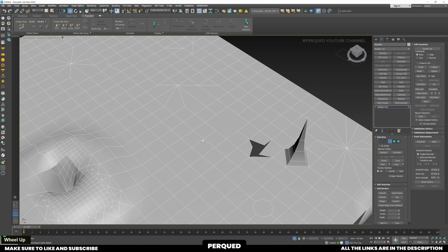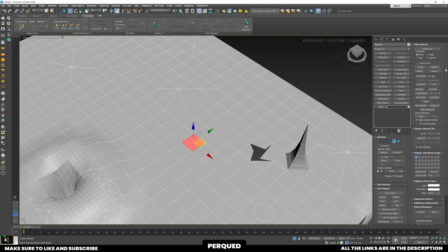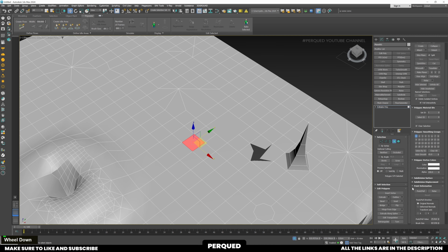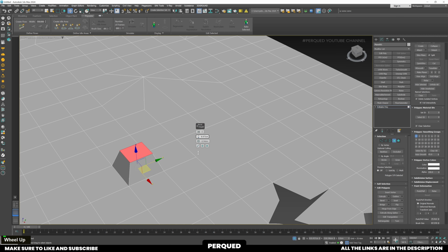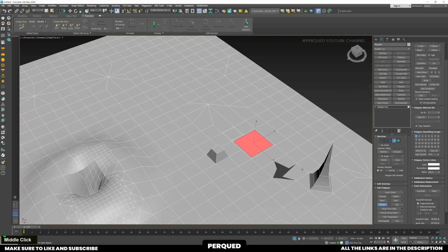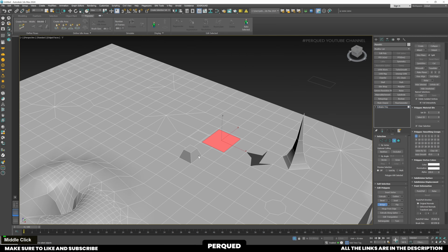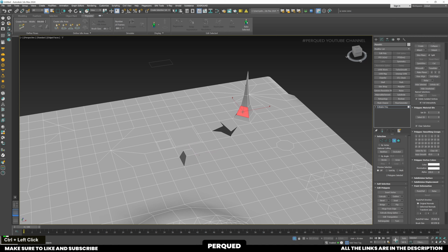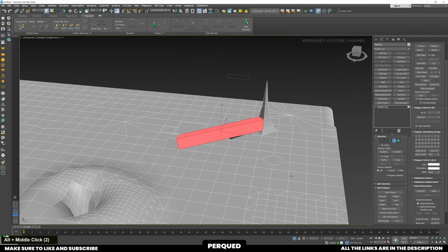Let's go to Polygon. We have Bevel, which is basically the next level of Extrude. You can extrude and add bevel with one setting. Next, we have Inset. With this, you can inset a polygon like this. Next, we have Bridge. With this, we can connect two polygons together. It has lots of inside tools. Make sure to check it out yourself.